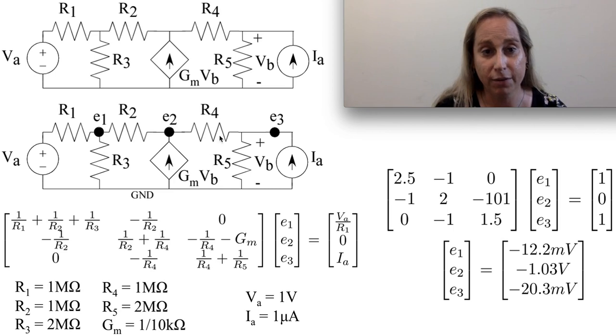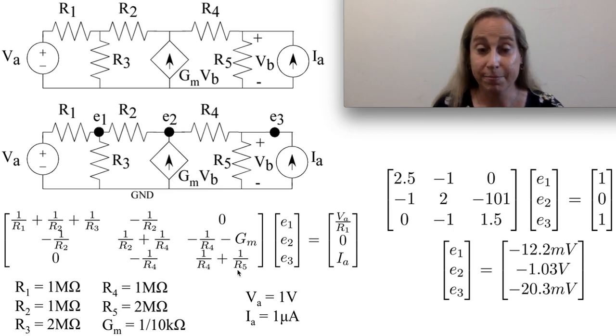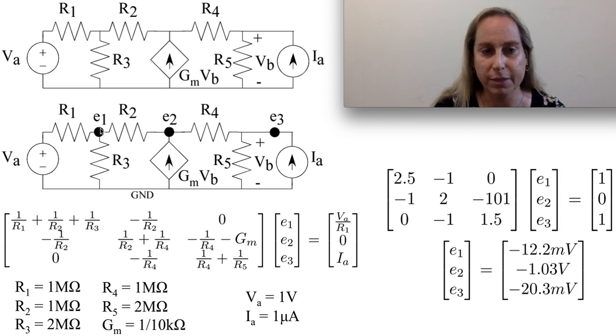And for the third one I get R4 and R5, so again I'm dealing with conductances, the inverse of the labeled resistances. Great. So now I can see the diagonals. The off diagonals are typically going to be the conductances between those nodes, such as R2 or R4, and we see those come out fairly easily.